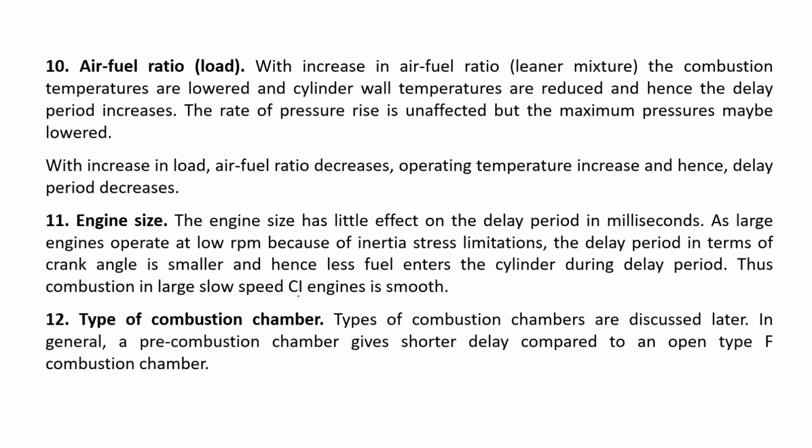Air fuel ratio: that is also going to be affected by the maximum. With increase in load, the air fuel ratio decreases, the operating temperature rises, and hence the delay period decreases. Engine size, no, it will not help much. Type of combustion chamber, yes, it helps a lot.